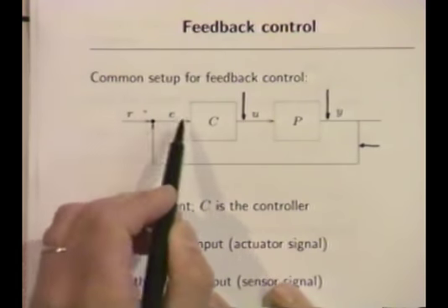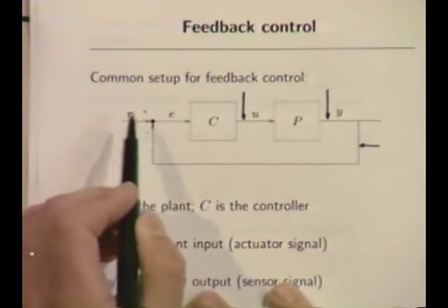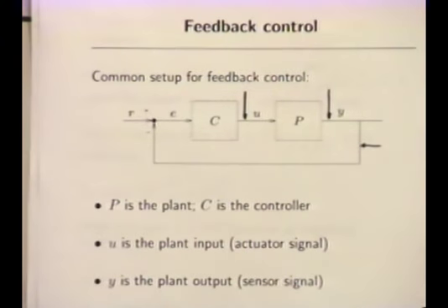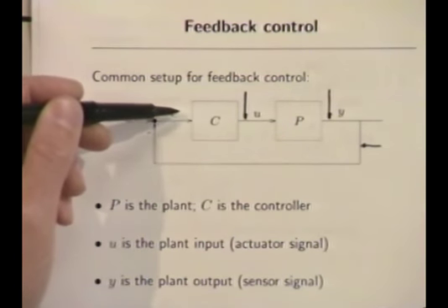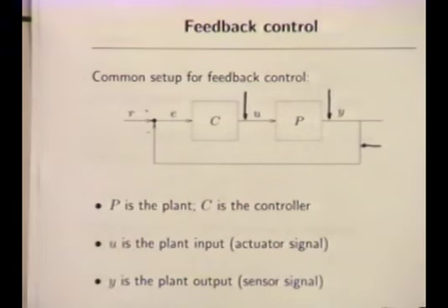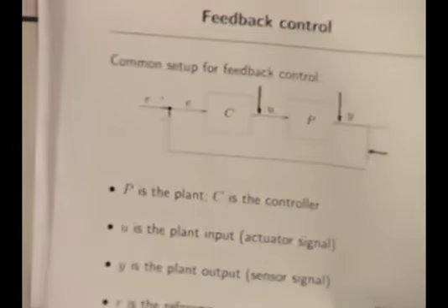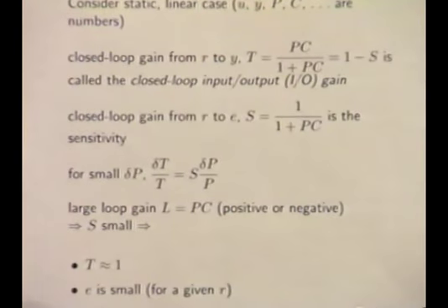So if that number, the closed loop gain from R to E, is 0.05, that has great significance. It says that when you put in 3 here, the error here will be 0.05 times that. In other words, the error will be 5% of the command signal. That's of the required signal. That's the idea. And you can work out the various details.